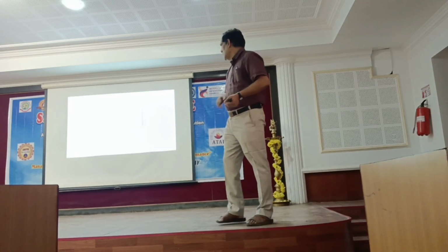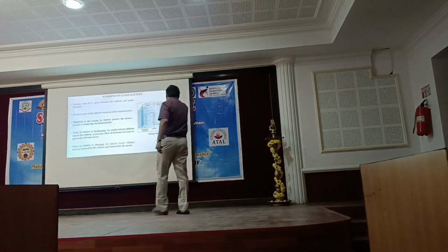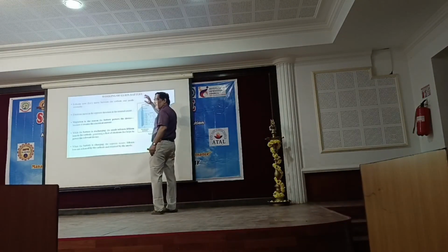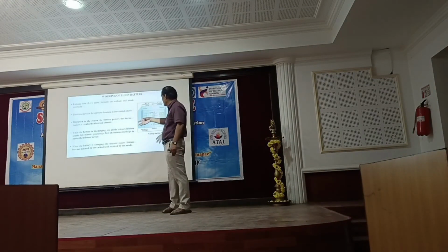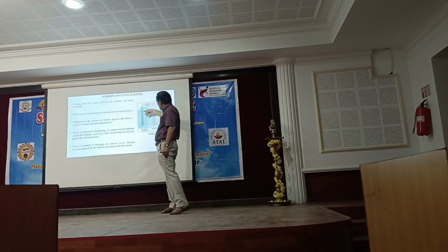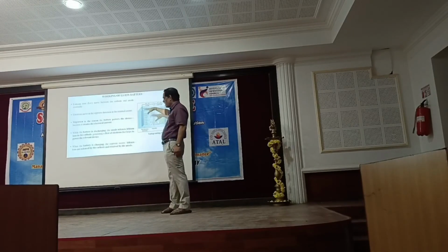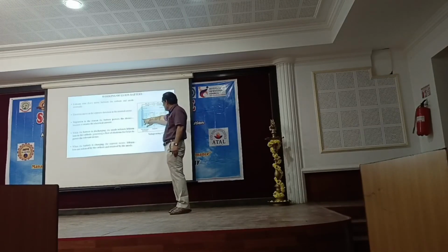I'm talking about designing the anode material and cathode material. I mentioned different types of cell design: cylindrical cell, prismatic cell, pouch cell. We need to look at the geometry features along with the material properties, electrical properties, mechanical properties, thermal properties, all such things. Not only for the anode and cathode, I should design the separator also properly.